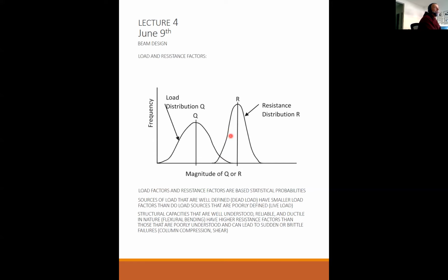What if I wanted the beam to be 36 inches deep? They actually built it to be 33 inches deep. That would make it weaker. There's all kinds of misunderstandings or mistakes, typos, just flat out human error that could cause this to be weaker than we had assumed. And it could be material properties. Maybe I wanted 4,000. Instead of getting 6,000, I actually got 3,500 PSI. That could happen. So there's all kinds of reasons why the actual beam may be stronger or weaker than what I had thought. So here's the point of the whole thing.